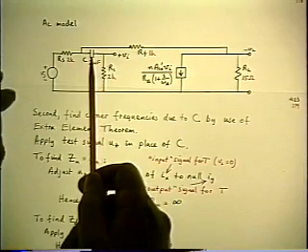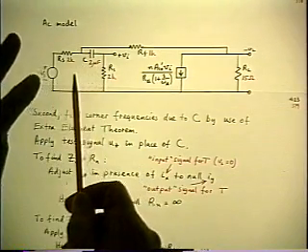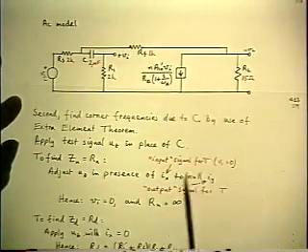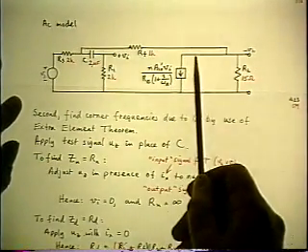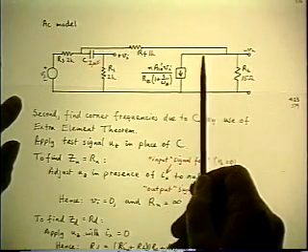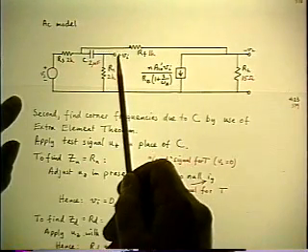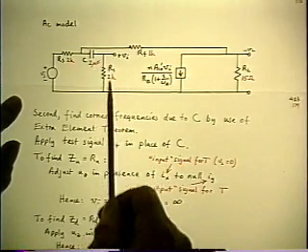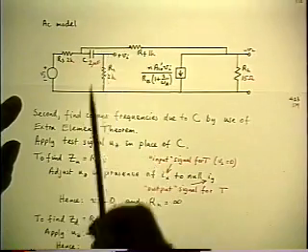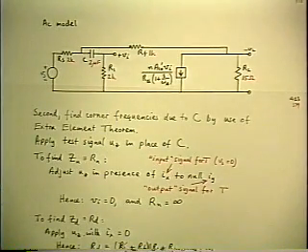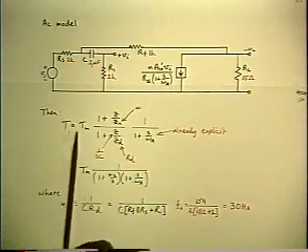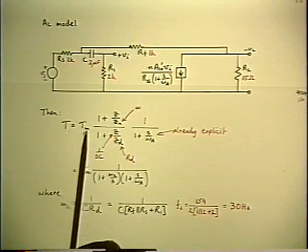Because we replace the capacitor with the extra source, Vs remains 0, Ix is restored, and this time we null the Iy, because Iy is the output signal for T. If you null the Iy, it propagates back to 0 Vi. If there's 0 Vi, there's 0 current in R1, there's 0 current to the second source, and Rn is infinite. So it goes away.